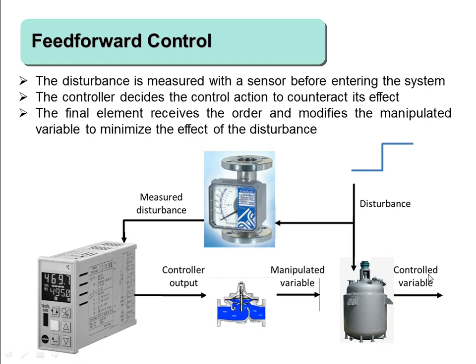If everything is done perfectly, we measure perfectly, and we have a very good model here, we will be able to counteract the possible effect of the disturbance with another effect, and then finally the controlled variable would not move from the operational point that it was maintaining before. So we are able to remove the effect of the disturbance by acting through the manipulated variable.